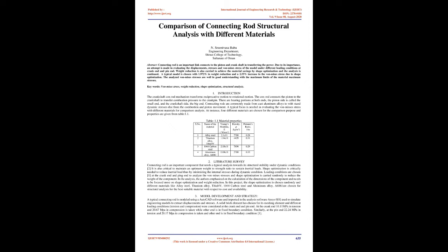Abstract. The connecting rod is an important link that connects the piston and crankshaft in transferring power. Due to its importance, an attempt is made to evaluate the displacements, stresses and von Mises stress of the model under different loading conditions at the crank end and pin end. Weight reduction is also carried out to achieve material savings by shape optimization, and the analysis is continued.